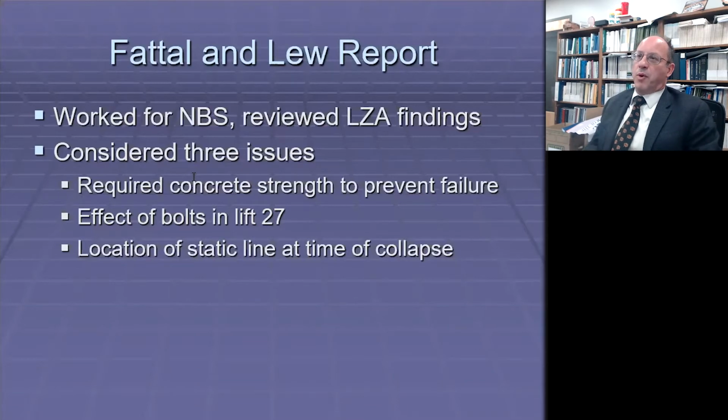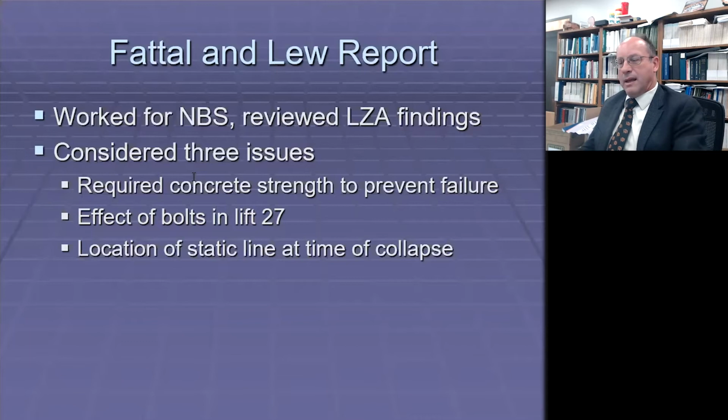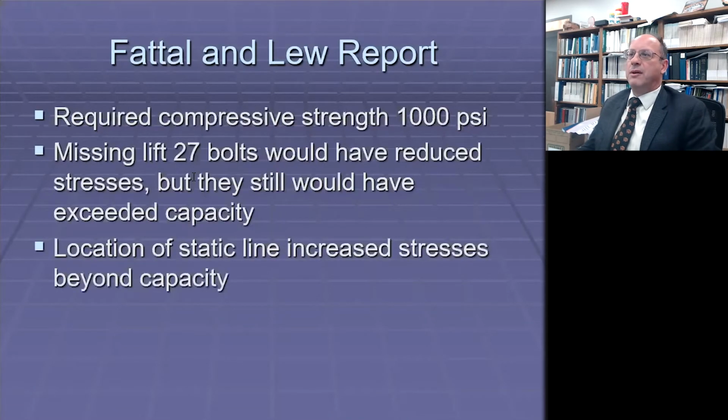Another NBS report then reviewed that and looked at the effects of the bolts and the location of the static line. But I think they kind of held with concrete strength as being the issue. They found that even the missing bolts would have reduced the stresses, but it still exceeded the capacity.